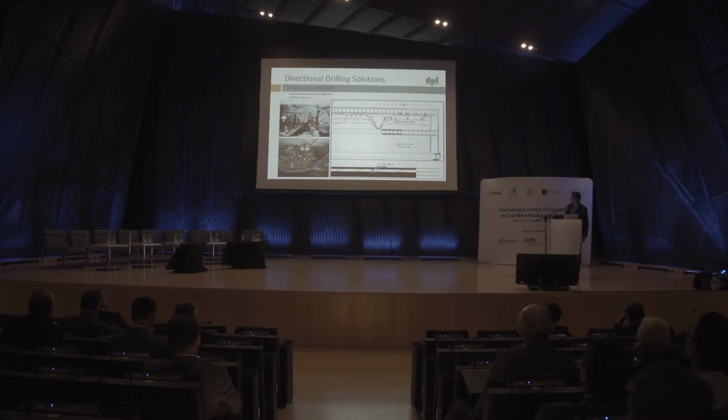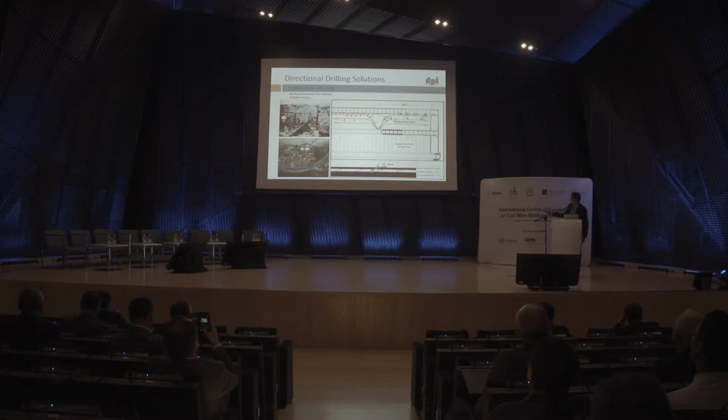What we did is we came along using directional drilling practices, and we started developing a directional drilling approach using what we call a bridge seam. This is the Mary Lee coal seam that's above it. It's only about 1 meter between the mined seam and the overlying seam. Using the Mary Lee as the bridge, which is competent and not as friable as the Blue Creek, we directionally drill out over 1,000 meters, and then we drop down into the friable Blue Creek seam to reduce its gas content.